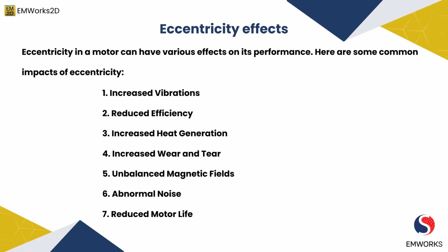Eccentricity can also cause uneven air gaps between the rotor and stator, and this will lead to unbalanced magnetic fields. This can result in torque fluctuations and reduced torque output, affecting the motor's overall performance and stability.